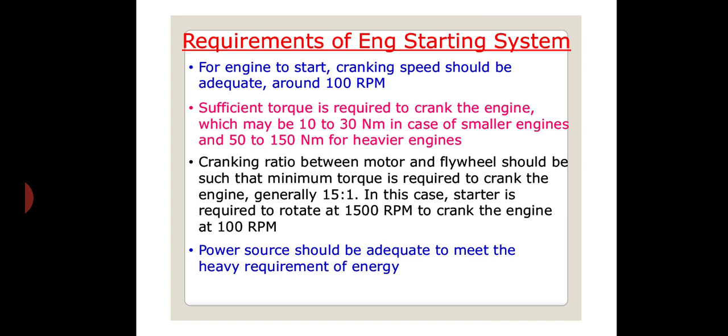In addition, if the speed is low, the unavoidable leaks past the piston rings, and likely leaks at the inlet and exhaust valves, would further lower the pressure and temperature during the compression stroke. The cumulative effect is that the pressure and temperature are not sufficient to ignite the fuel which is to be injected at the end of the compression in case of a CI engine.